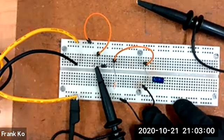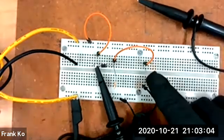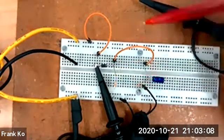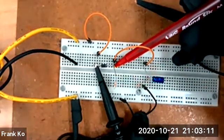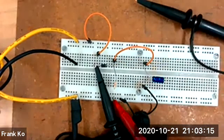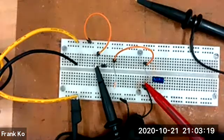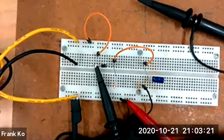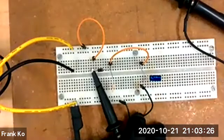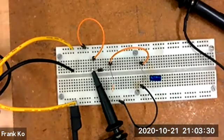Okay, so is our circuit build showing the addition of the capacitor to be in parallel with the load resistor? They are connected at the top of the resistor to the top of the capacitor, and the bottom of the resistor hooked up to ground, as is the negative side of the capacitor. So do I have a parallel connection? Have you completed this connection, students? I will put this on pause and come and assist.